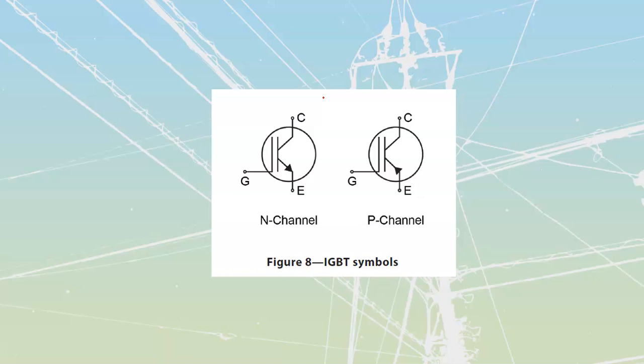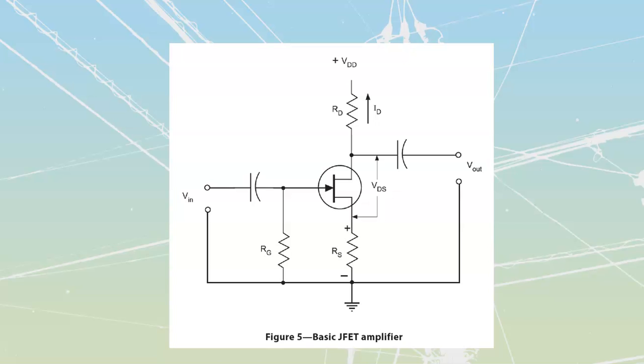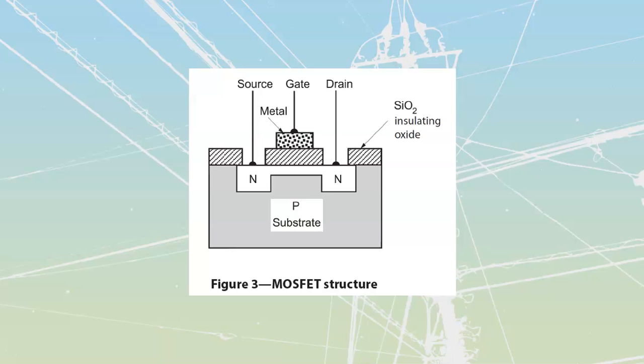It does have forward blocking operation. That's going to be similar to the MOSFET, where we're just going to go and throttle down the channel, but it has far lower I squared R power losses for a given current than a comparable MOSFET. If I take a look at my MOSFETs, all the way up top here, here's my actual MOSFET. I'm going to actually dissipate a fair amount of heat as I'm traveling through that channel back and forth over there because I don't have complementary. It's a unipolar type that I have over here, where it's only traveling through the N type of material.